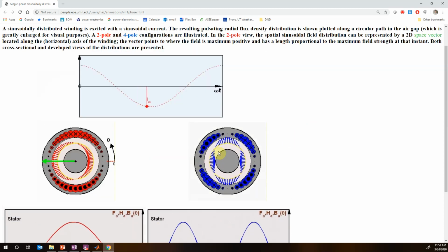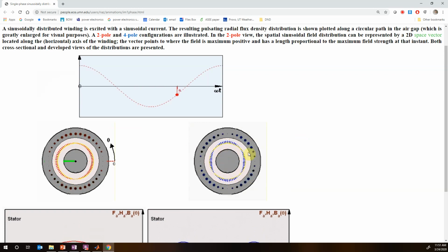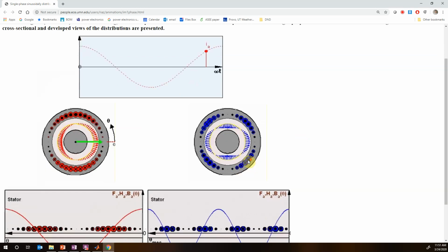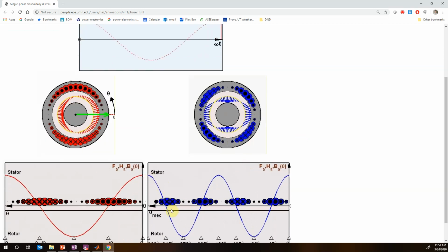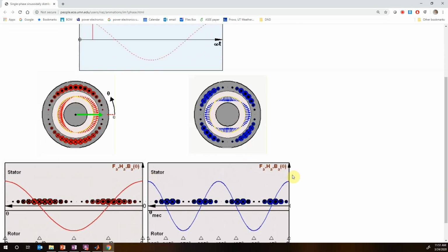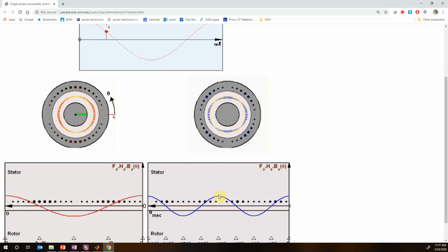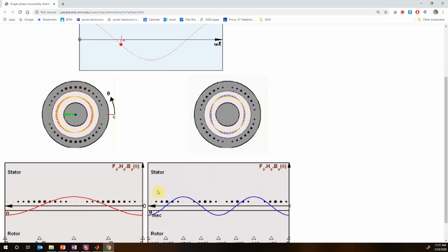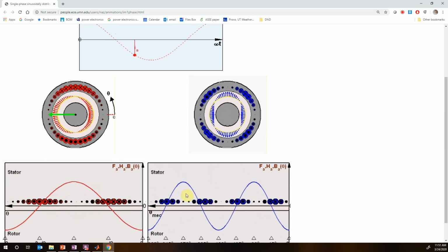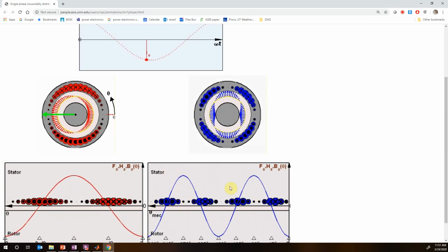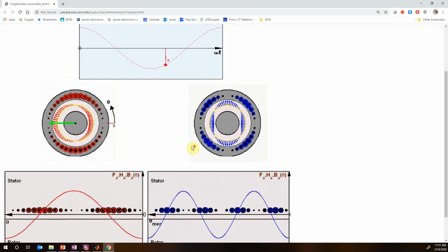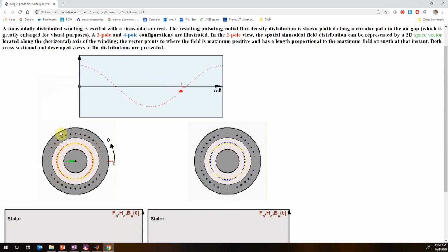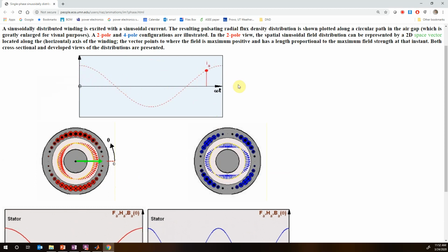This one over here shows that this has a winding that's twice as fast. So this is called a 4-pole system, where this one over here was a 2-pole system. And in this case, we're just increasing our winding percentage, or I guess our spatial frequency of the winding. It still has a sinusoidal shape and it still goes up and down with current, but now it varies twice as fast. So these are called sinusoidal windings connected to one current source, where this is my one current source.